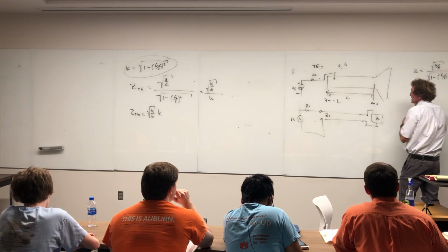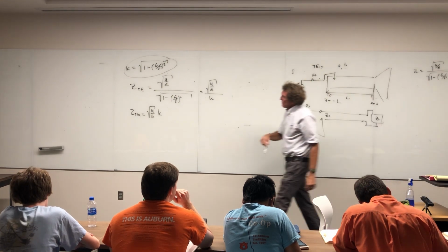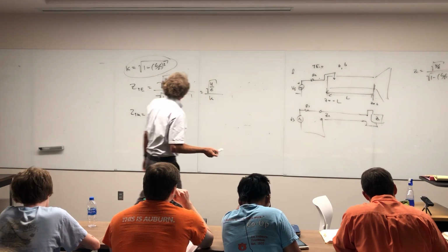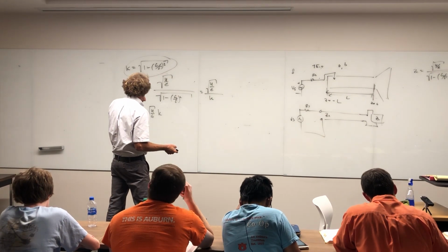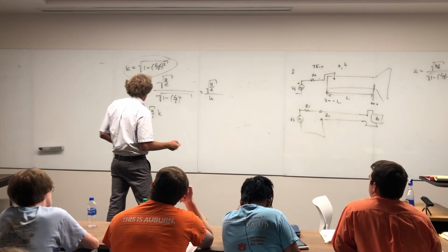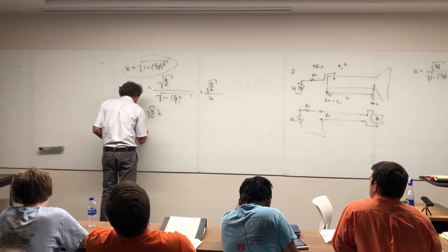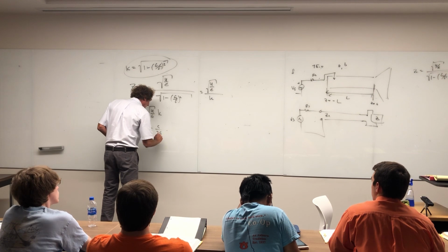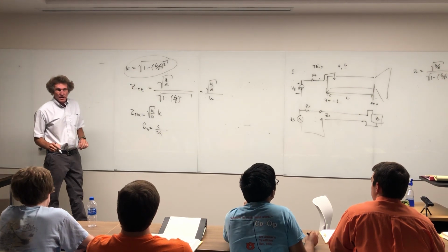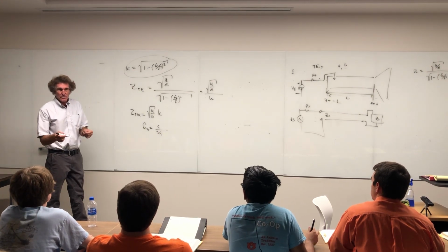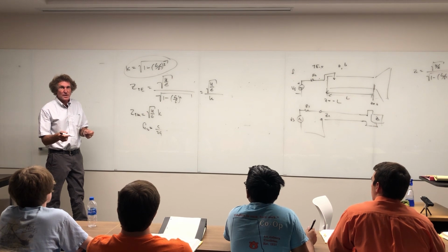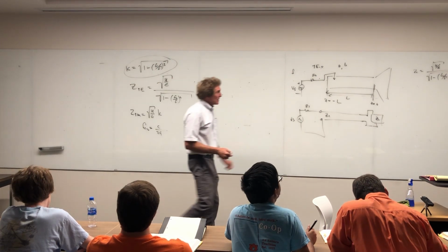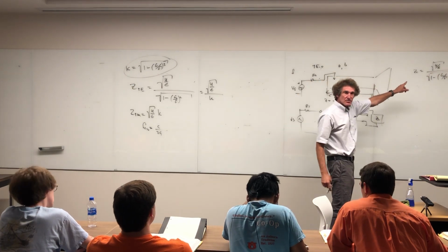So now you have to calculate FC. For the 1-0 mode, FC is equal to C over 2A, right? Remember I showed you what it reduced to when n is 1 and n is 0, class? That's what you get. You calculate that. You come here and you find the characteristic impedance.